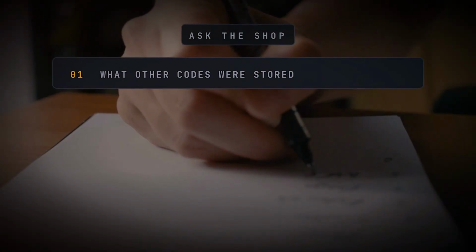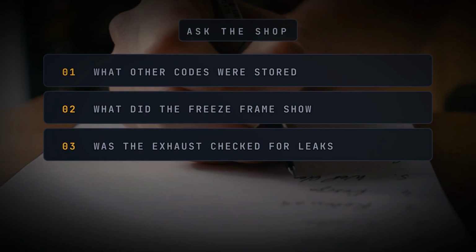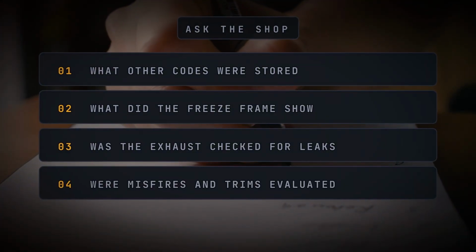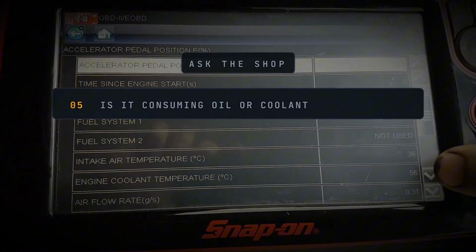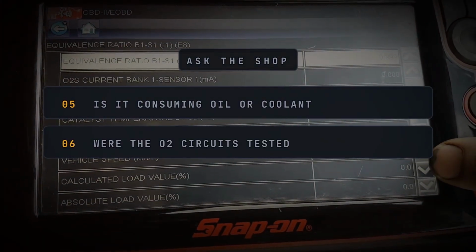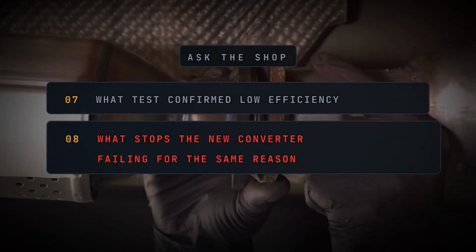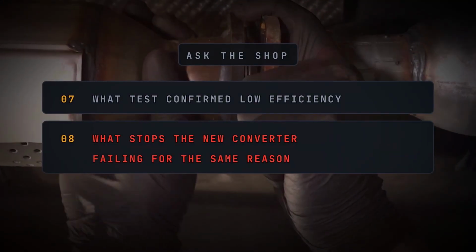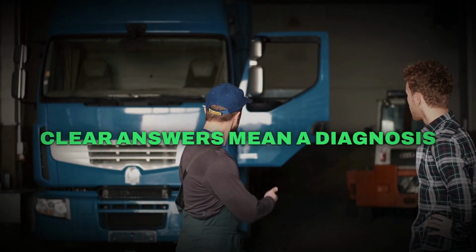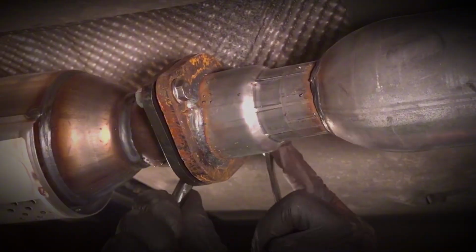What other codes were stored? What did the freeze frame data show? Was the exhaust checked for leaks? Were misfires and fuel trims evaluated? Is the engine consuming oil or coolant? Were the oxygen sensor signals and circuits tested? What test confirmed low catalyst efficiency? And what will prevent the replacement converter from failing for the same reason? Clear answers indicate a diagnosis. The code saying catalytic converter is only the beginning.